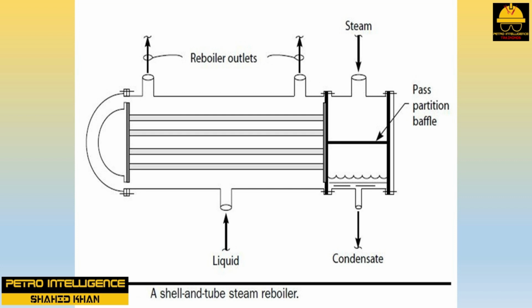If the reboiler is a thermosiphon, or natural circulation reboiler, then low process side pressure drop is important. For a horizontal reboiler, it is easiest to obtain a low pressure drop for the fluid being vaporized by placing it on the shell side. The steam enters through the top of the channel head of the reboiler. Any superheat in the steam is quickly lost to the tubes. Superheating steam does very little in increasing heat transfer rates in a reboiler.